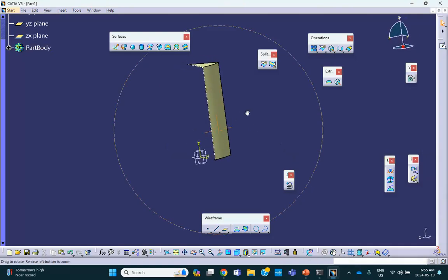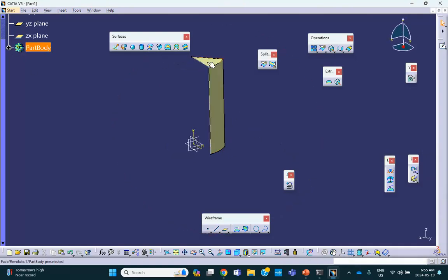If you go this route, you don't have to join these two because of the way you did it, it's essentially a single piece. Notice that when I select it, the whole thing is selected. In the other one, when I selected, it was extract one, just the top piece. Extract two, just the curve piece. And I deleted extract three, of course. But here, that's why I joined it. So when I selected join, the whole thing is selected. But here is all one thing. You mesh this thing, there's going to be the same node from the elements on the top and the bottom.